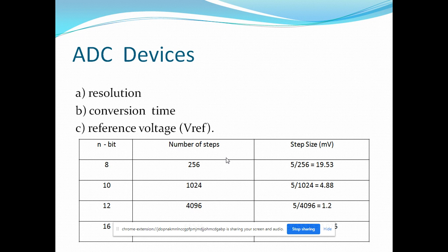In previous microcontroller devices that we have studied, like the 8051, there is no ADC available on chip. We have to interface an external ADC such as the 0804 or 0808 for converting the analog values fed to the microcontroller into digital first. Then we can apply these digital outputs or discrete values to the microcontroller, so that it will process these signals and do further operations as per the user requirements.